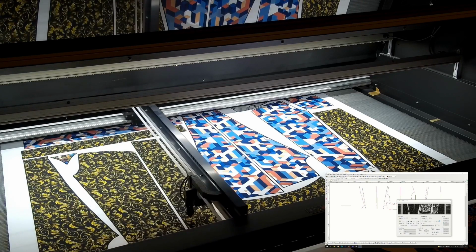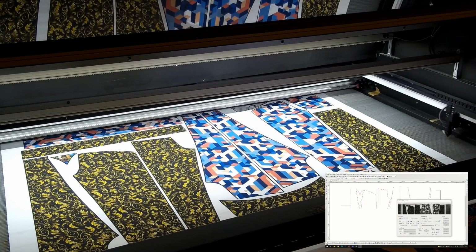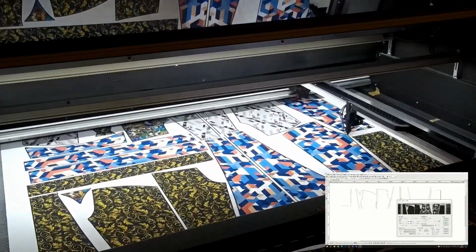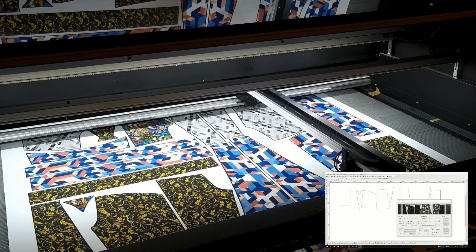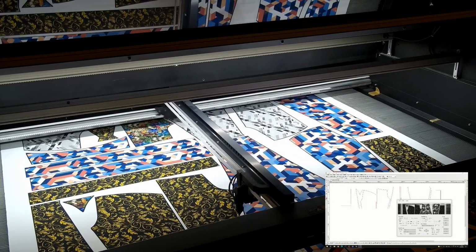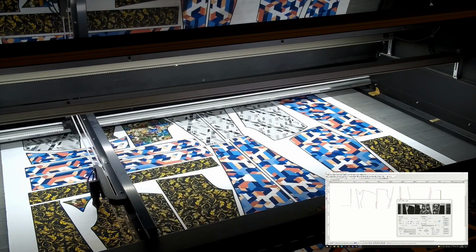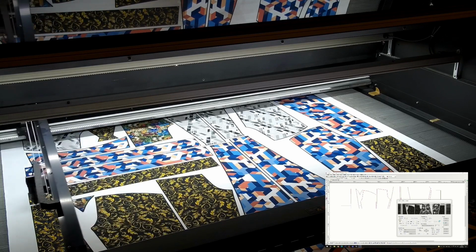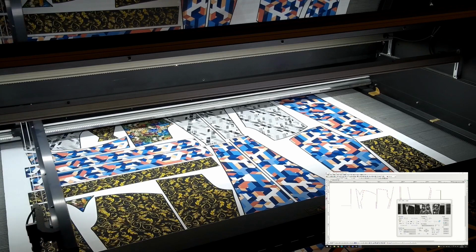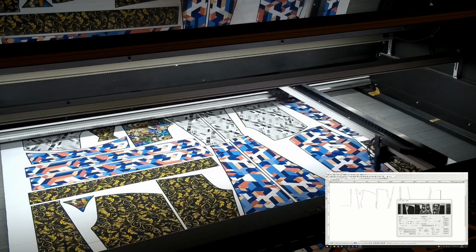There is one thing you need to consider. There is around about a 1 centimeter distance in between jobs. If you link them up to each other or they connect completely, the vision will not generate a cut path in between two shapes. It's going to, of course, consider that one shape. So you need to have about a 1 centimeter, 10 millimeter white space around your material to be able to generate a complete contour.